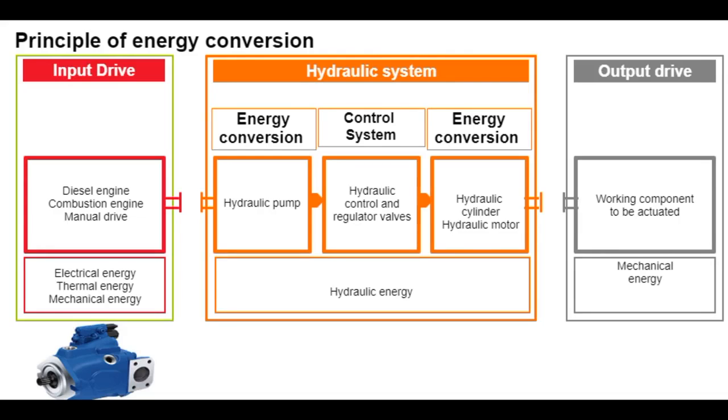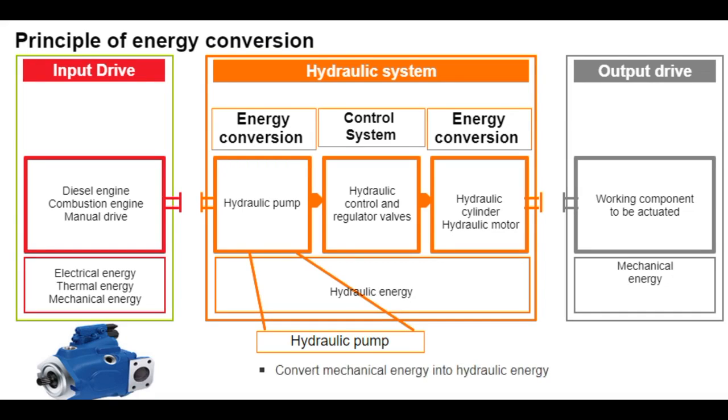In a hydraulic system, hydraulic pumps act as energy converters. They convert mechanical energy coming, for example, from a diesel engine into hydraulic energy. The mechanical energy is used to generate flow in the hydraulic circuit.